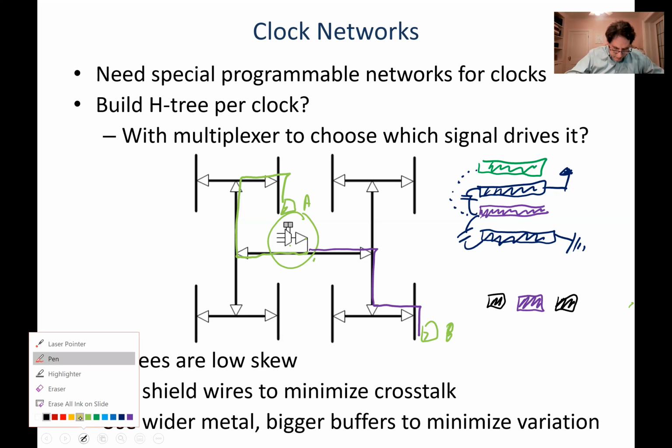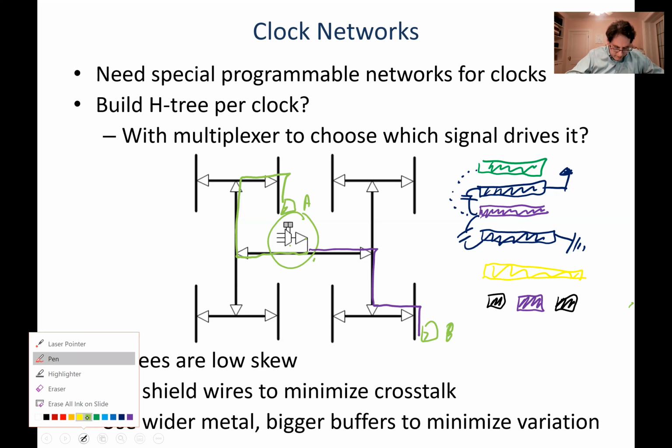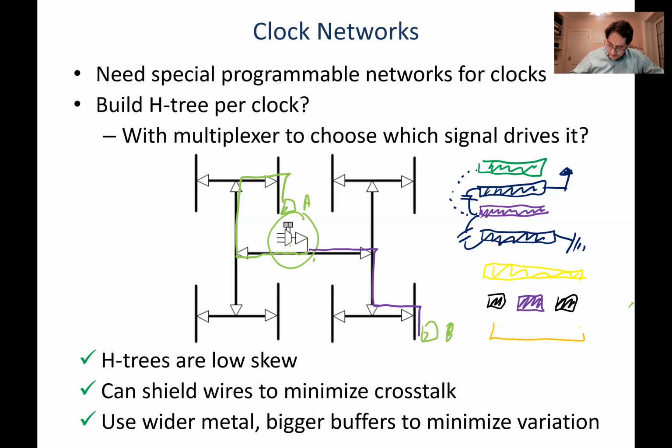And I think Diana's question is, well, what's above it? There are other wires above it. So on this layer above it, there's a wire or a whole bunch of wires. And on the layer below it, there are a whole bunch of wires. They're going in the other direction, okay? Because they're going in the other direction, there is a capacitance to this clock, but it's very small because they're not parallel for very long. These wires are perpendicular to each other.